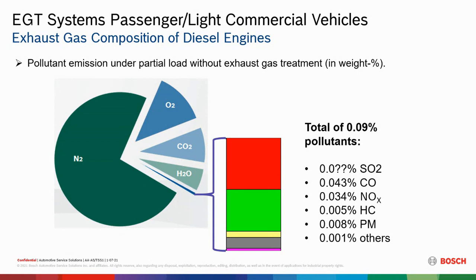Before electronics in the mid 90s, the particulate matter was grossly bad with that being produced from these vehicles due to the fact that diesel engines run better with more fuel. Obviously, the more fuel you give it, that thing's a powerhouse, and that was the whole key thing. And most people that had diesels, if they could turn those pumps up and crank that fuel into those cylinders, just gave that vehicle more power to the max. But we had to kind of limit that with electronic diesels, and not that you can't do that today, but we try to shy away from that because we're trying not to overload that aftertreatment system and produce that black smoke out the tailpipe.